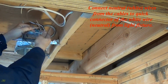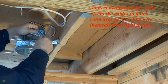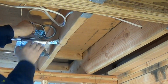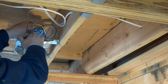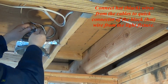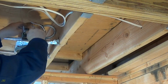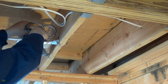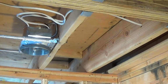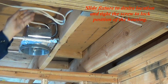Connect neutral, white wires from the cables to quick connector of the white wire, neutral from light fixture. Connect hot, black wires from the cables to quick connector of the black, hot wire from the light fixture. Close junction box cover. Slide fixture to desired location and tighten the screw to lock position of the housing.